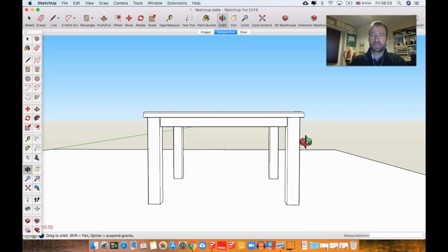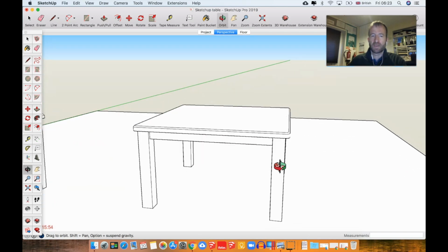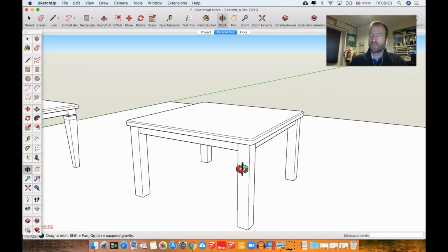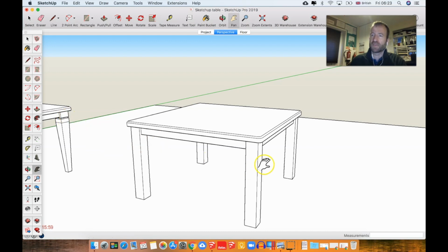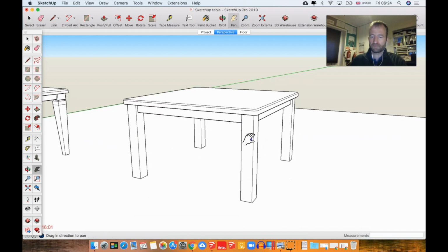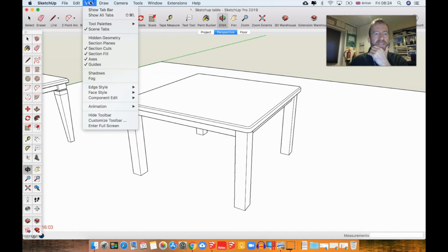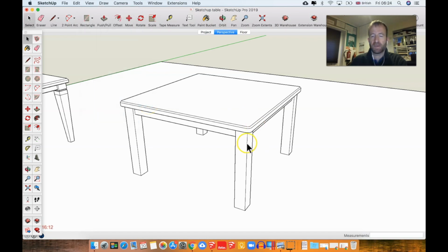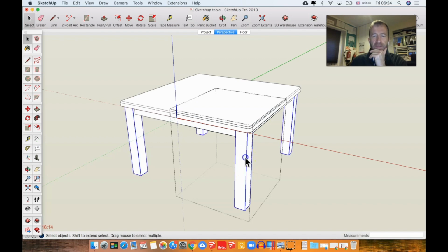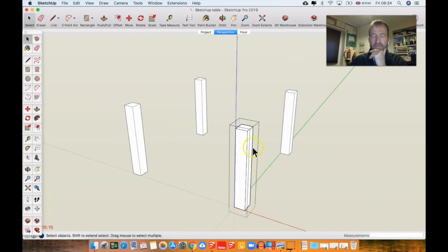And now let's just see if we can show you the tapering and the other little feature we've put in here. So I'm going to change my settings to not hiding similar components, but hiding the rest of the model. I'm going to double click again to get into that leg. And I want to push pull the top down, let's say 120.